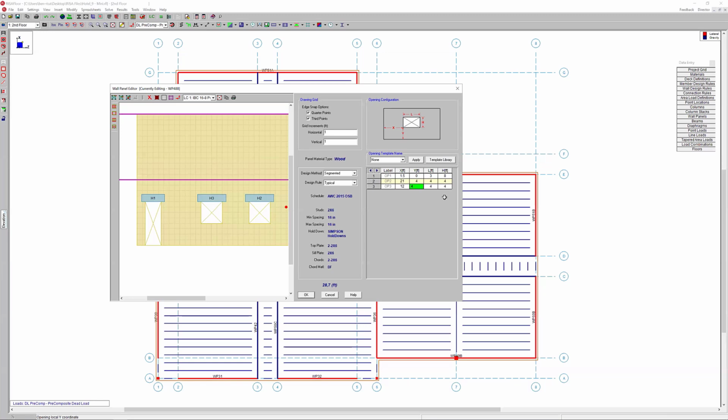As I do that, I can also utilize the same spreadsheet features that we have in our regular spreadsheets. If I put everything in wrong, or maybe the architect comes back and wants us to shift everything, I could say I want to shift this in the X direction. So I right click and choose math on block, and add in 2 feet. Shift everything 2 feet over. So I can easily update and change that as well.